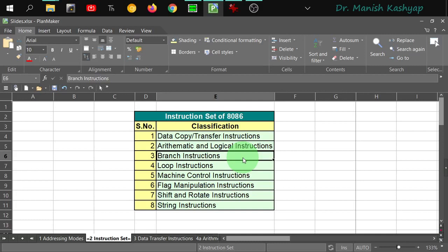Or if you are inside the data segment and you want to make an inter segment jump, you can jump into maybe the extra segment. That is also possible. In that way, we have near and far jumps. Like in function calls, we discussed that we have near call and far call, similarly in these jump instructions also, we have near jump and far jump instructions.